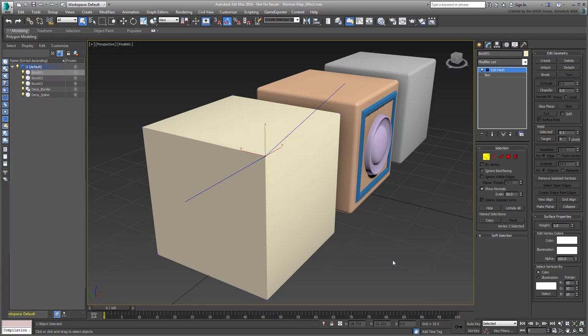The more vertices you have, the more faces you have, and the more normals you can adjust. In low poly modeling, you are restricted as vertex count, and therefore normals count, is usually kept to a minimum. So, instead of working at a vertex level, you generate normal maps to work at a pixel level.